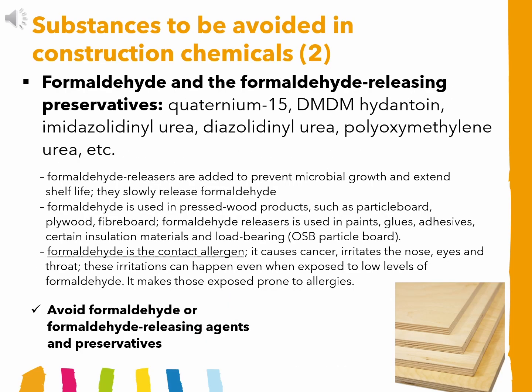The next group to avoid is formaldehyde and formaldehyde-releasing preservatives. These are often used in paints, adhesives, and certain types of pressed wood products, such as particle board or plywood. Formaldehyde is a known contact allergen and carcinogen. Even low-level exposure can irritate the eyes, nose, and throat, and increase sensitivity to allergens. Select materials and chemicals that are free from formaldehyde and formaldehyde-releasing agents.